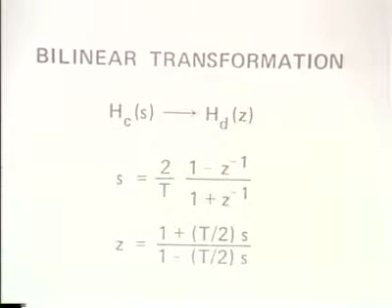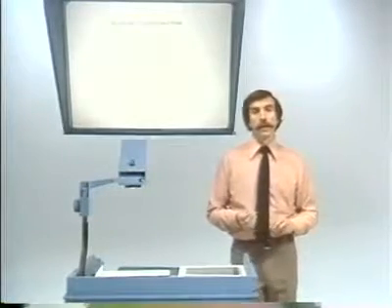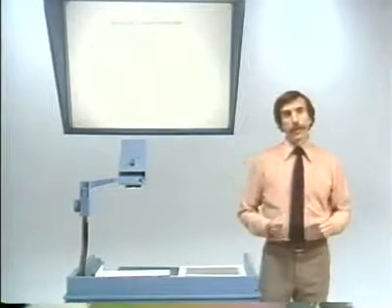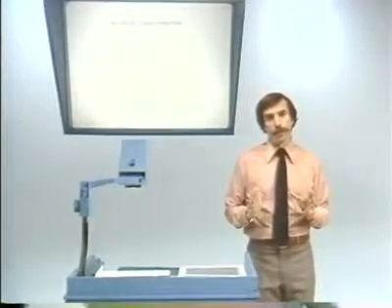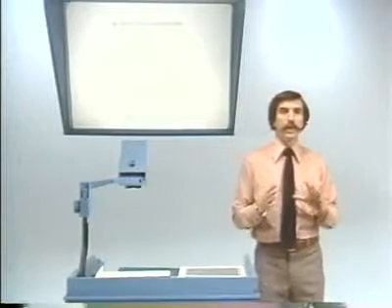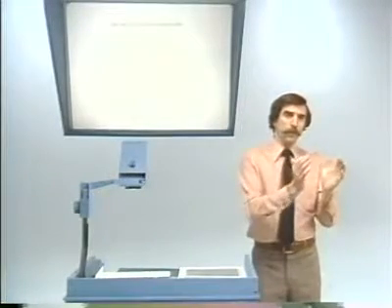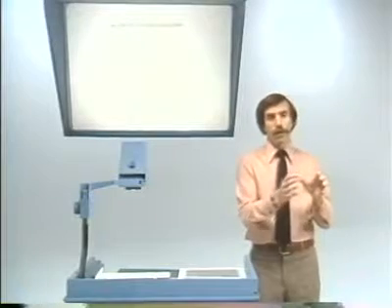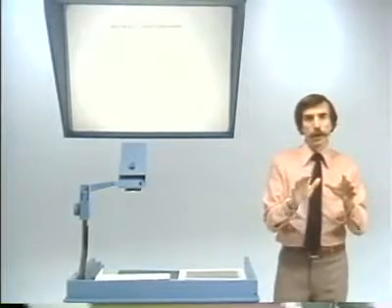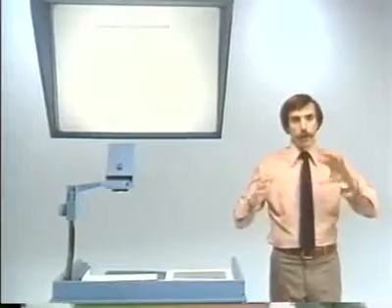And let me just say quickly and in passing that although we won't go through this, the notion of the bilinear transformation can be tied to the concept of taking the differential equation for the continuous time filter, converting it to an integral equation by integrating enough times on both sides, and then converting that to a difference equation by approximating the integrals with the trapezoidal rule.